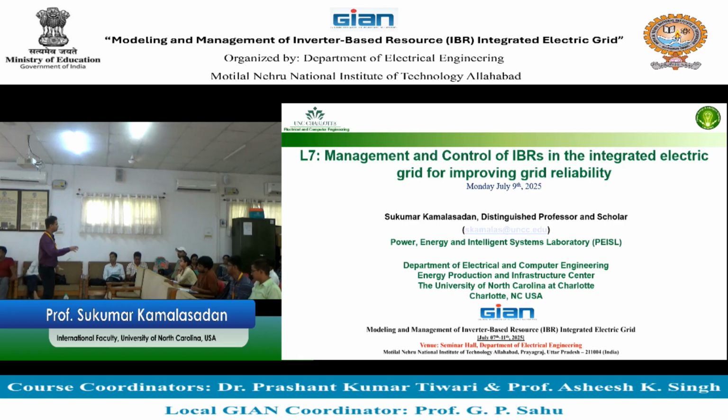Now, where do you connect this energy storage? It's up to you. You can connect the energy storage along with the PV farm and then convert the DC to AC. Such PV farms with storage are generally behind the meter, meaning not seen by the utility. On a rooftop or some places you always have a battery connected to the PV, and then you have some DC bus. I'm not going to draw the picture, but you can see it: PV, battery connected to DC, then to inverter, then to AC.